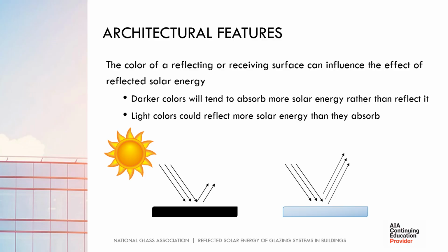Many building cladding materials and fenestration components are designed to reflect solar energy to either provide better performance, specific appearance characteristics, or improved longevity. These types of products could provide for more direct reflected solar energy to adjacent materials. Building materials such as aluminum and copper flashing, brass kick plates on exterior doors, coated and non-coated glass products, aluminum or vinyl siding, and painted wood, to name a few, can and do reflect solar energy onto adjacent materials.